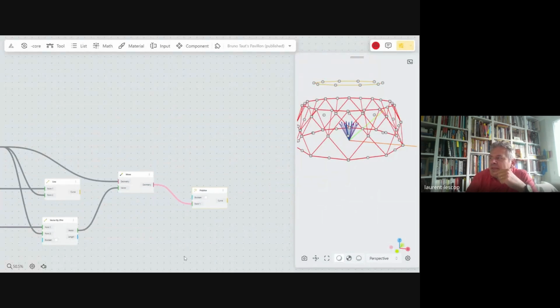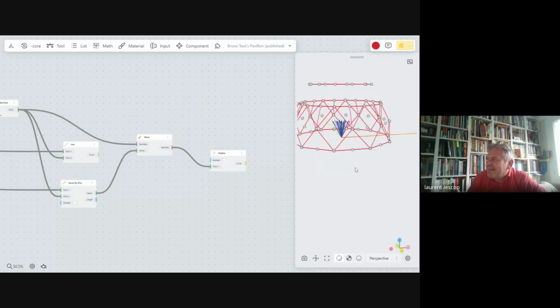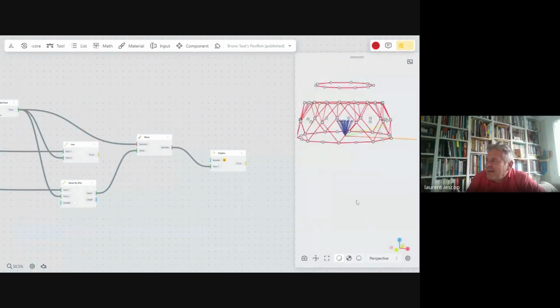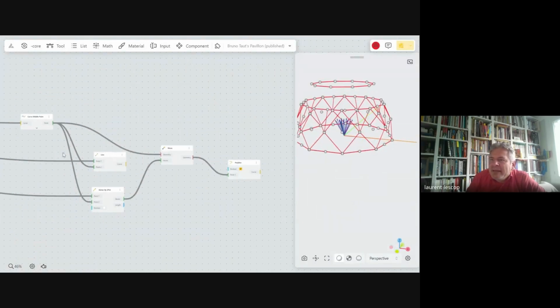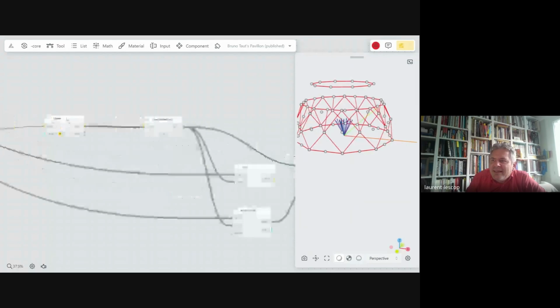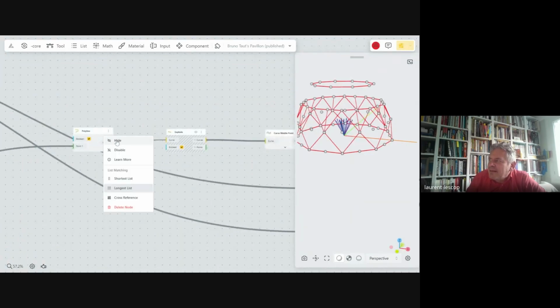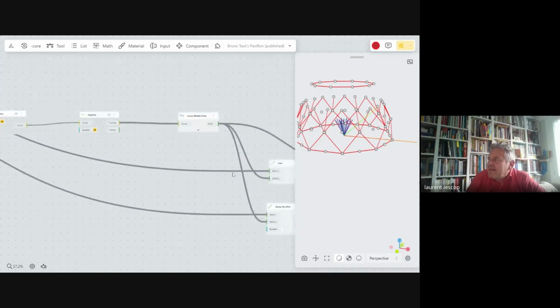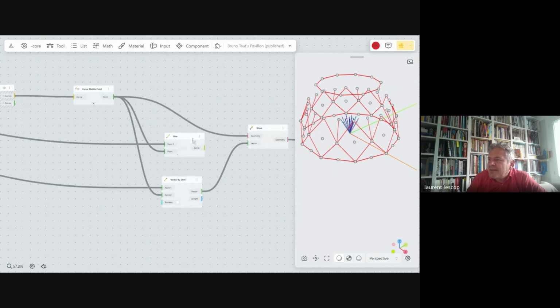Maybe we can do a competition to find the best way, or the easiest way to do this. But I didn't find a better way to do that. I think it's the only way to do it. Maybe, I don't know. Explode, so hide, polyline, hide, and then I will have to create my triangles.